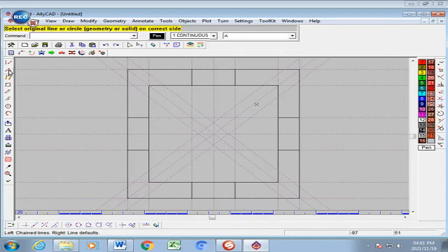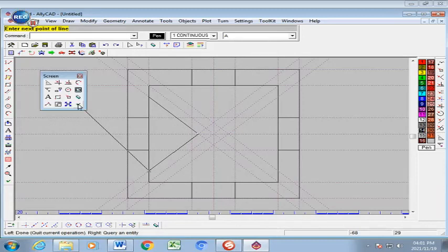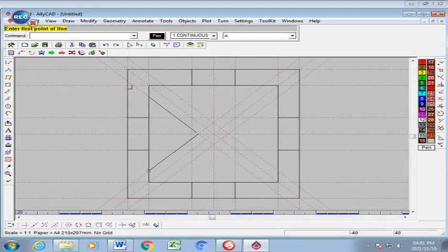Now I can go to my chain line. And click on there. And then from here I'm going to draw a line to my center there. Click. And to that point over there, click. Now, I want to detach. Detach. Go back there. Click here. To my center. Click. And click in that corner.